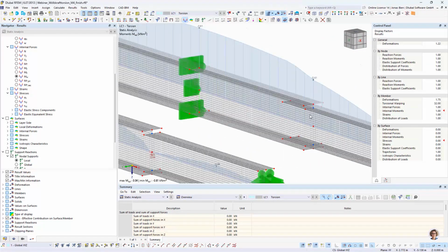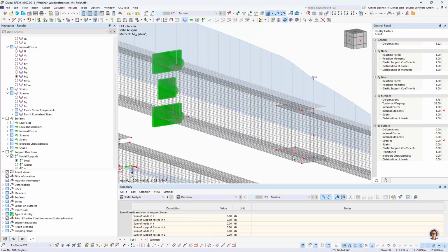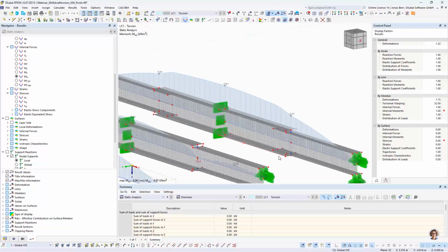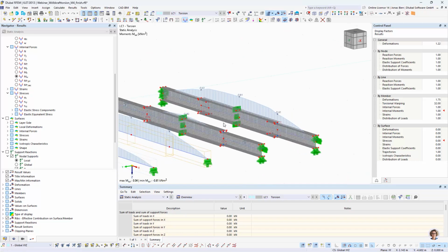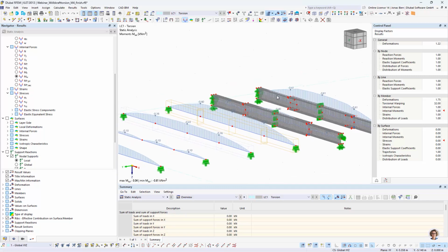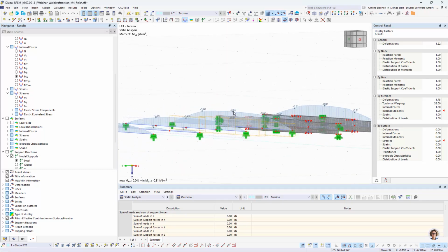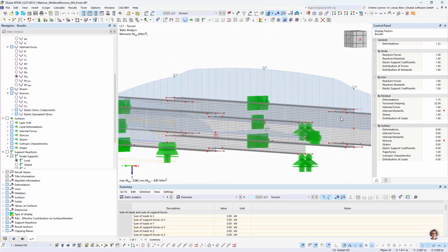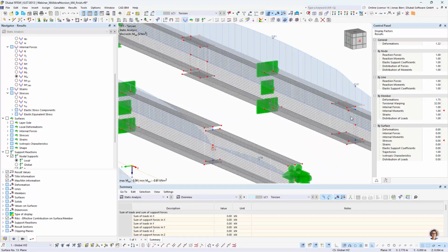And then the third configuration, where we have elongated the flanges of the smaller section into the larger section, we can see that here we have pretty much continuous warping. In this case, we even have a slightly higher warping moment at the middle, because we here have a section that has a much higher torsional stiffness, that has 4 flanges.